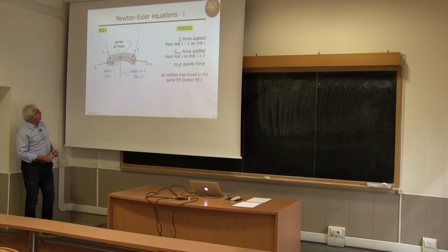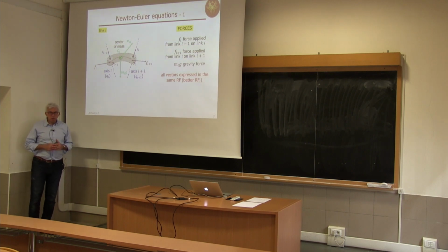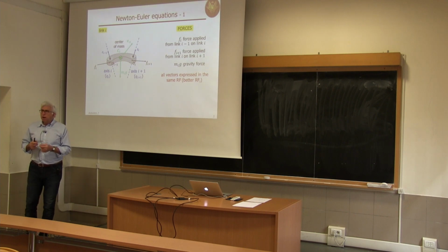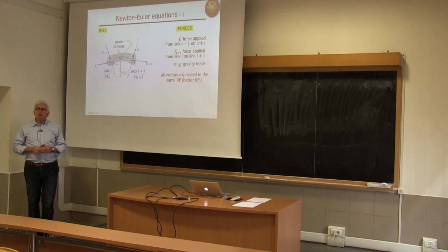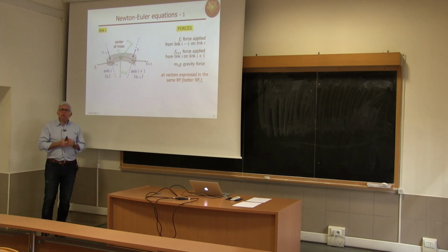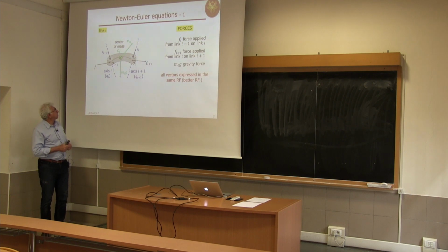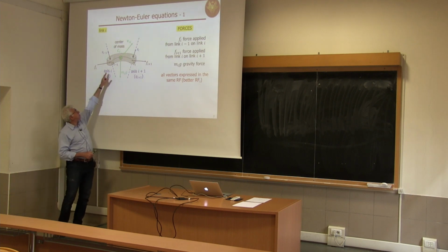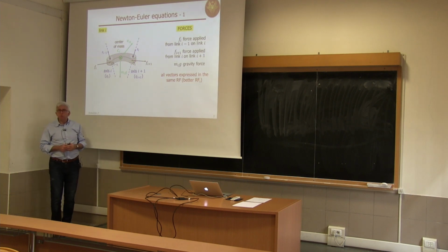What else? Let's call f i, and this will be a recursive notation, the force that the link i minus 1 applies to link i through the joint i. And we consider this force applied to the origin of frame i minus 1.